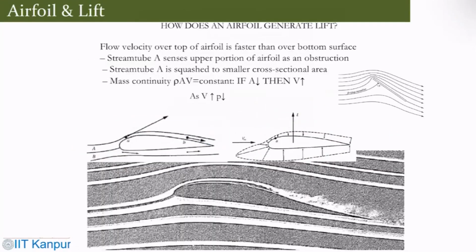So how does an airfoil produce lift? If you see, this is a typical flat plate, or here we see the airfoil. The flow velocity over the top of the airfoil is faster than on the bottom surface.